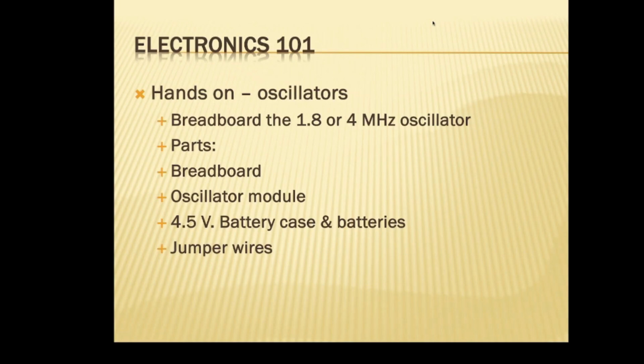At any rate, built into this thing is a little crystal. A crystal, when a voltage is applied to it, will oscillate at a certain frequency, and it's very, very accurate. So they take that little crystal, put it with some integrated circuitry, and come up with a little generating circuit that will give you out one of these pins a 4 megahertz square wave signal. It just works. It's wonderful. It's a great little thing.